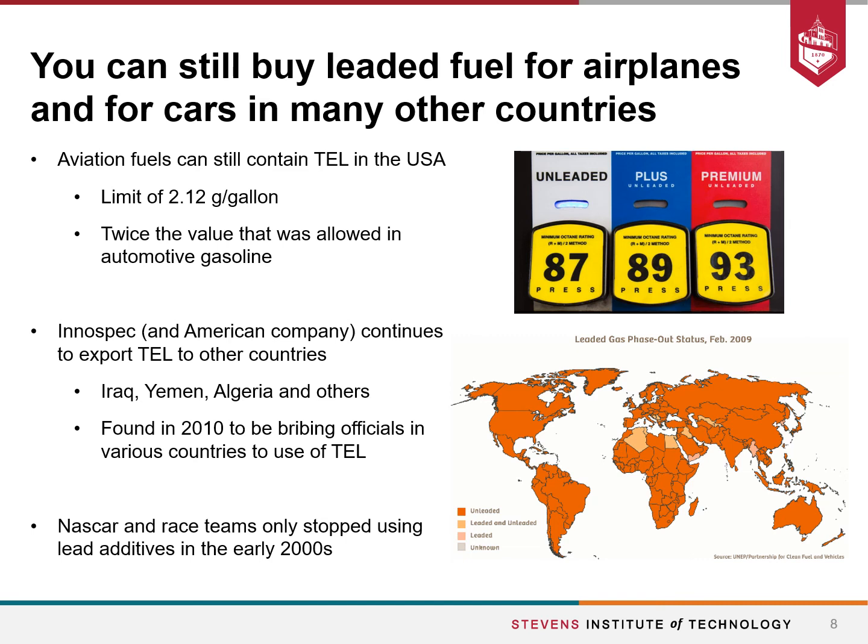Some racing competitions, NASCAR for example, still used lead additives in the early 2000s as well to help prevent auto ignition. And so the final image I'd like to finish with here is this image of the pumps in the top right. You see this unleaded moniker whenever you go to get fuel. Now perhaps you understand a little bit more about what it means. It means that there are no lead additives put in those fuels. You might also see that the fuel contains up to 10% ethanol. That's the additive we are now using to control auto ignition here in the United States.